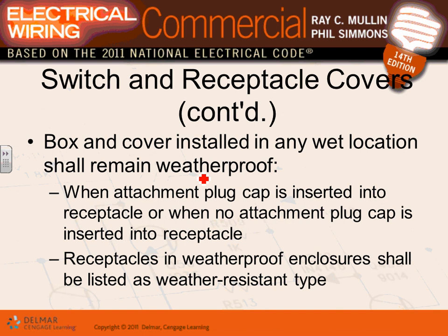If you have boxes and covers installed in a wet location, in 2000, oh, that has been for a while, guys. Any receptacle installed in a wet location must be, listen, for anywhere, in use covered. You guys see that bubble that you put your receptacle, you plug in and the bubble sits like this? In use cover, they call it.